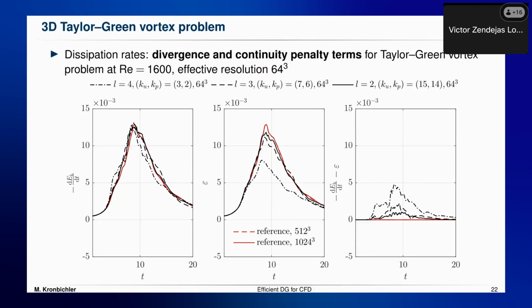Yes, the general observation is that you capture more of this small scale turbulence. There are some issues with the high order discretization, at least with the basic discretization methods. Some people call it the kinetic energy bump. Essentially, because of the dispersive and dissipative properties of high order DG methods with upwind fluxes, you are actually getting too little dissipation on some of the scales.